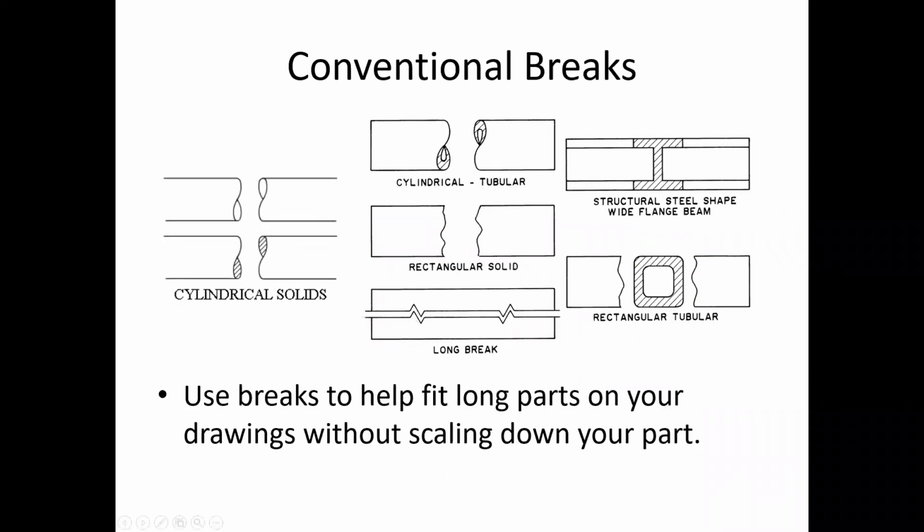The idea of those breaks is just to help give the reader of the drawing an idea of the shape of that profile, what's going on with the ends there. And it also lets you put long things on regular size sheets without having to go really down in scale. What's really the downside of going to a really super small scale? Does anybody know? Why not just make everything on A size and just scale it?